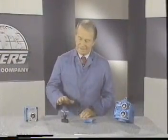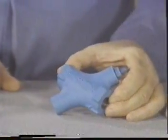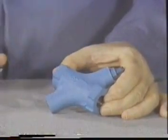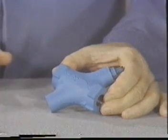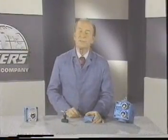Here again is our simple needle valve. This one's a non-compensated flow control. It's adjustable, and it has a check valve built into it for reverse free flow. It's installed in the circuit by means of threaded pipe ports.